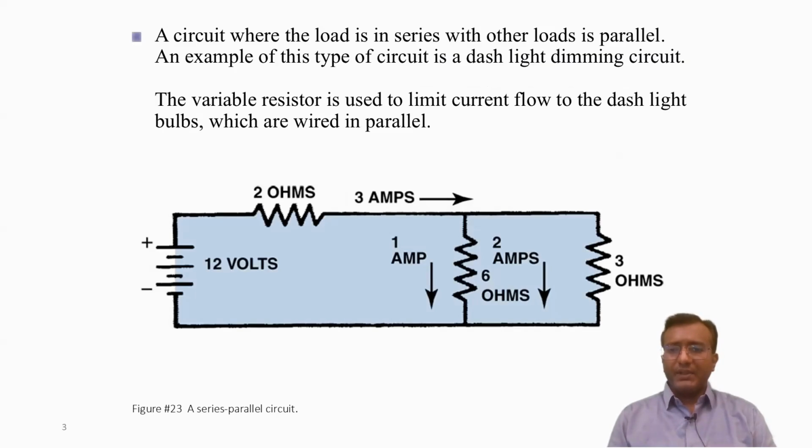Here we can see a total of 3 resistors in the circuit. 2 are in parallel combination with each other, and for that we can determine their equivalent resistance. This equivalent resistance is in series with the other resistance. So this is the best method by which we can simplify a complex circuit and solve it step by step to determine the unknown quantities.